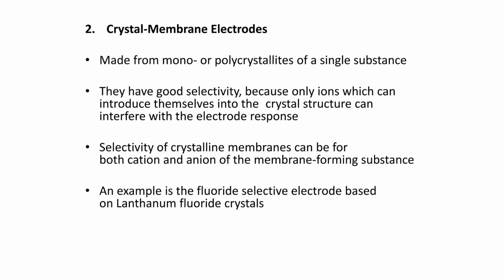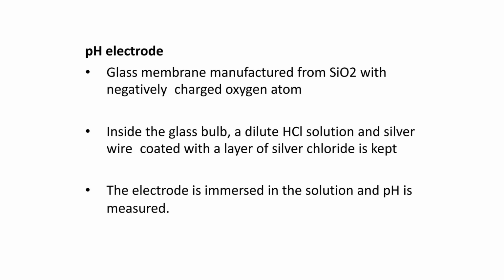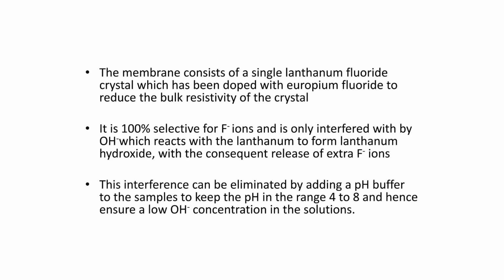And the exact logarithmic relationship between the ionic concentration, or chemical activity, is governed by the Nernst equation. It is given here. Here, the standard pH electrode and the specialized ion selective electrodes are discussed. First, it is contrasted to the highly specific pH membrane. Other ion selective membranes will not be entirely selective to their target ions, and they can permit the passage of secondary ions present in the test solution.